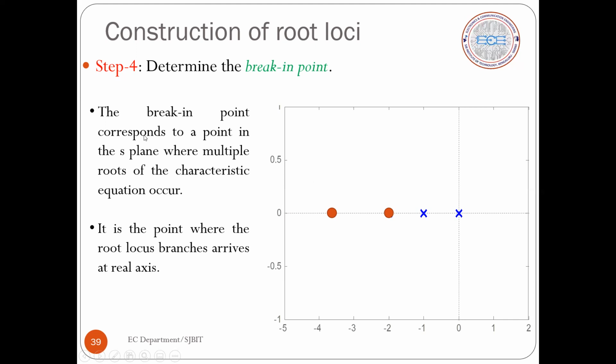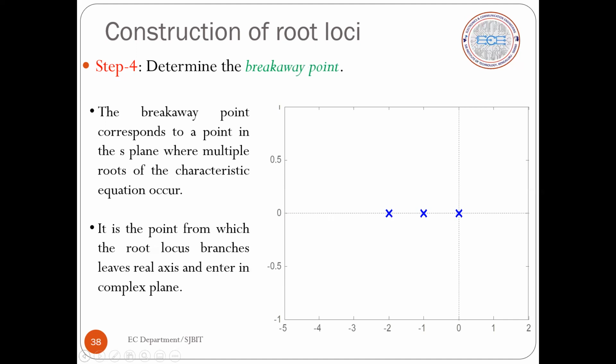Okay, so here we have an explanation for a breakaway point and a break-in point. The breakaway point corresponds to a point in the S-plane where multiple roots of the characteristic equation occur. It is the point from which the root locus branches leave the real axis and enter the complex plane.